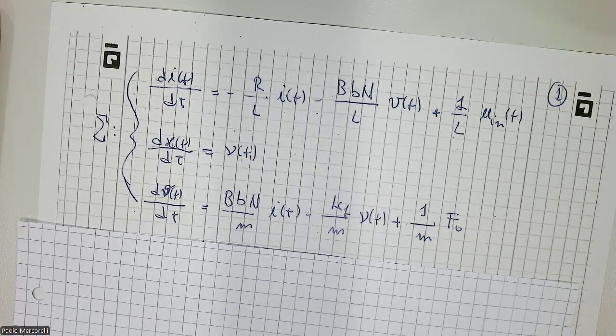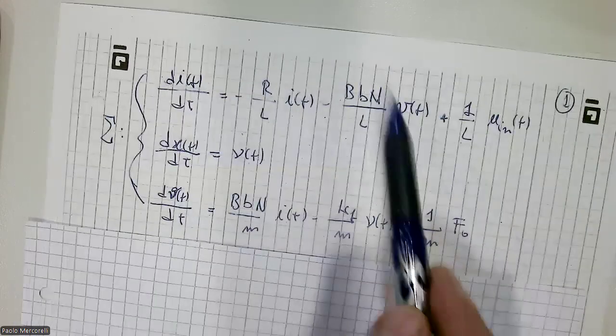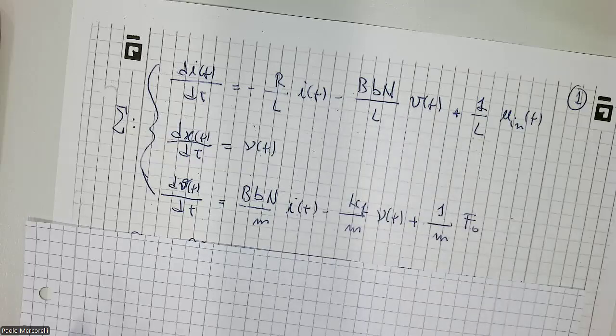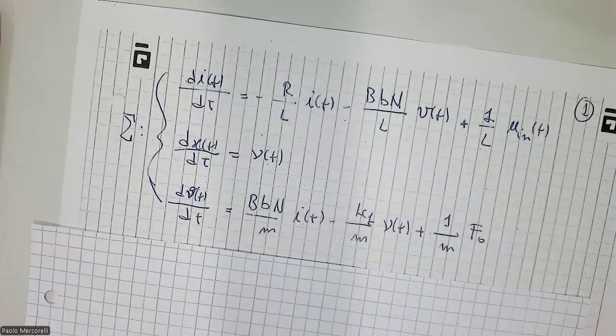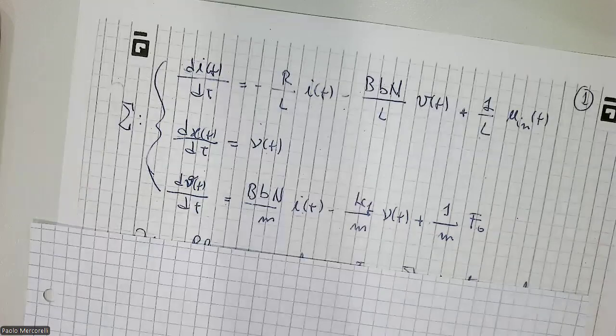This means we have an induced voltage which is not stepwise constant, because the induced voltage depends on the velocity. But if the velocity is not constant, the induced voltage is not constant. We cannot say that the current is constant or stepwise constant. Anyway, it's not exactly constant because of the structure of the magnetic fields, but somehow constant even though stepwise. This means everything changes. You have to consider also the inductance.